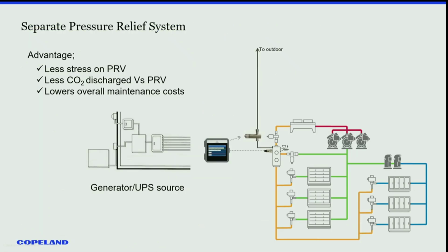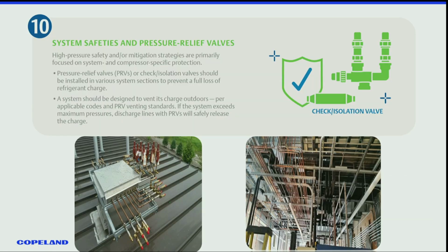And also burp valve, you talked about burp valve. Sometimes you can hook up a generator to your controller, and as you approach your 650 pressure relief, you burp a solenoid valve or an electronic valve to relieve the pressure in the flash tank. It drops, and then when it comes up again, you just burp it. So you're not losing large amounts. You don't have a leak event, but you are managing the pressure.